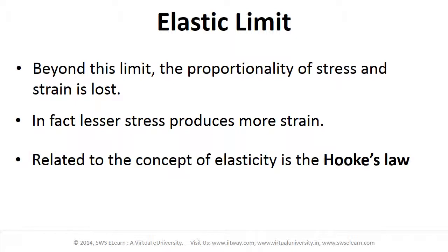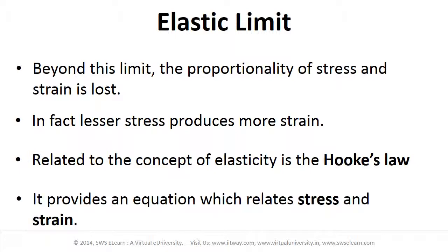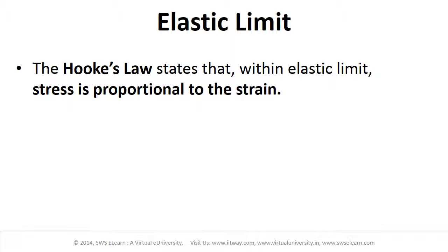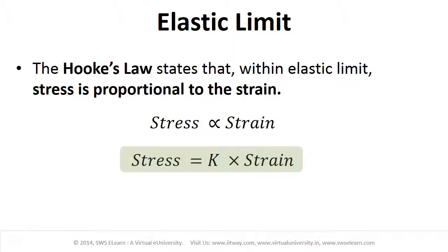Related to the concept of elasticity is the Hooke's law. It provides an equation which relates stress and strain. The Hooke's law states that within elastic limit, stress is proportional to the strain, that is, stress proportional to strain. Therefore, we can write the equality equation by introducing a constant of proportionality. Thus, stress is equal to constant of proportionality capital K into strain.